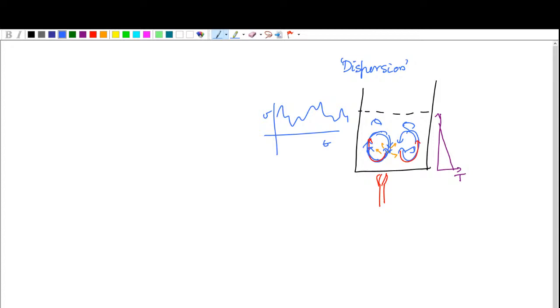Whereas if it is carried by molecular velocity fluctuations, it's called diffusion. And you can estimate the magnitude of the dispersion and diffusion coefficients if you just know the characteristic length and the characteristic velocity. The diffusion coefficient, if you recall, has dimensions of length square time inverse. So it is a characteristic length scale times the characteristic velocity.